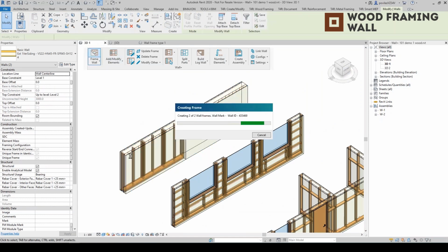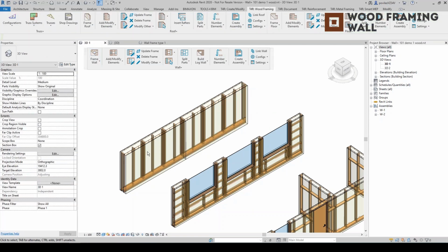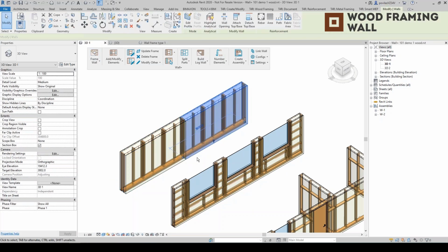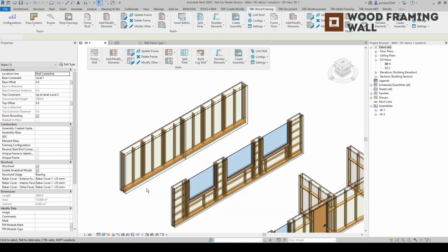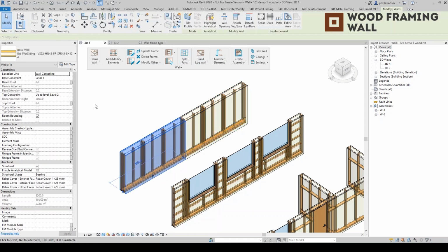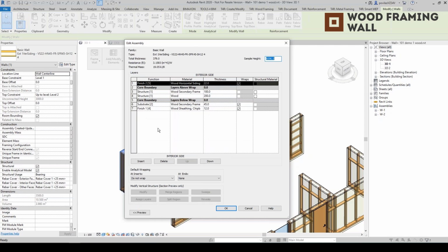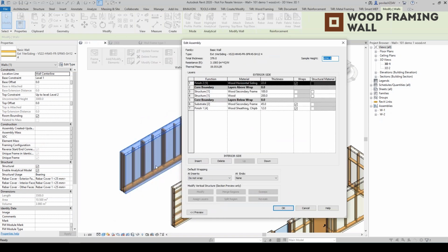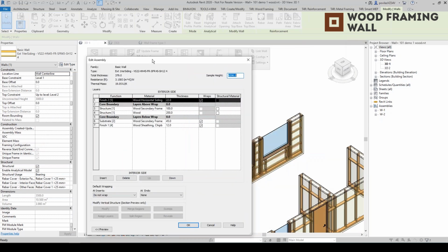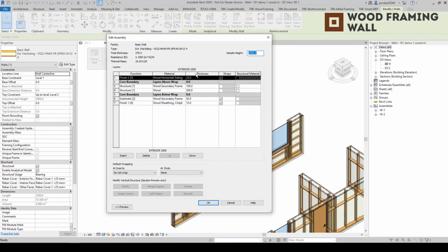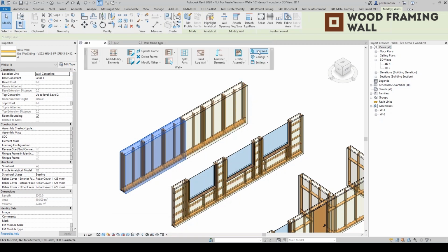Okay, so the other important thing, like I mentioned before, once you have your Revit model in place that contains all native Revit elements, if you are using walls, in this case, we ideally want to define our wall as accurately as possible. I appreciate this could change during the project, but the more information we put in, the more effectively we can build our frames. So this one was quite important to define our function, material thicknesses, what is structural material or not. And once we do that, we later on use link wall function.